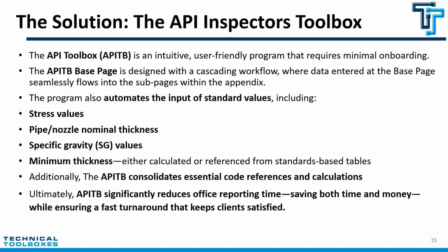Okay, the program also automates the input of standard values, including stress values that consider design temperature and build dates. Okay, pipe and nozzle nominal thicknesses based on size and schedule, specific gravity values from selected products, minimum thicknesses either calculated or referenced from standard-based tables.